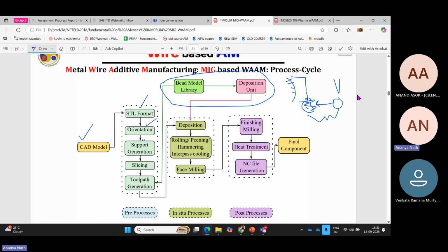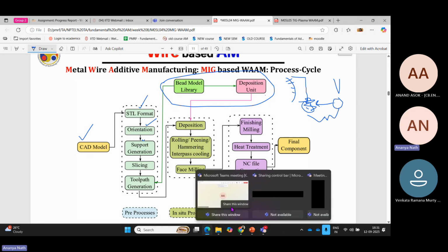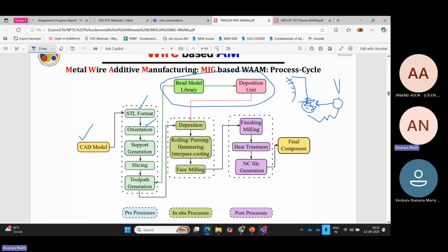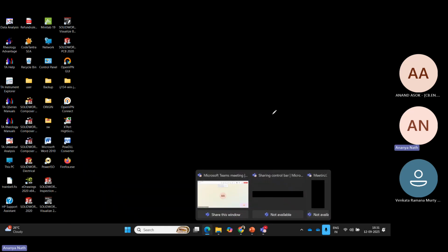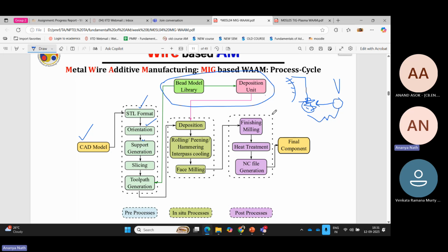If you are talking about additive manufacturing, you cannot help but get a very high cooling rate, because additive manufacturing is all about high cooling rate and high deposition rate, because of which you get a very small bead. That we already know and we agree, right? And now, if you are doing deposition at elevated temperature and power, then because of the high heat gradient, the cooling rate is even faster.